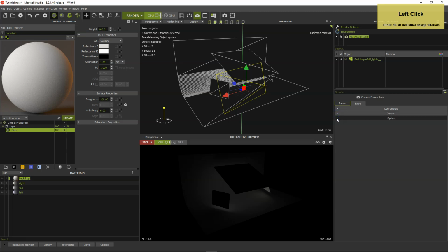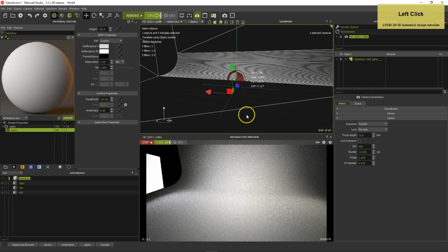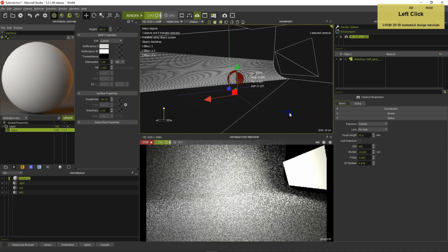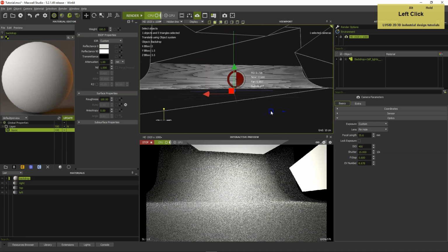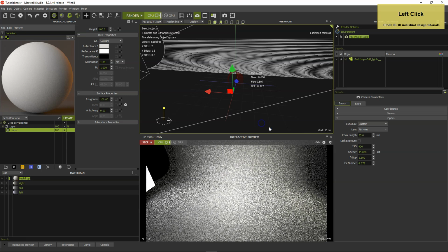While setting up the beech wood, bristles and logo, it's a good idea to use the pinhole camera to eliminate the depth of field. Activate the camera in the viewport and select a product photography lens. Then set the f-stop, shutter speed and ISO for a nice depth of field for the final render.